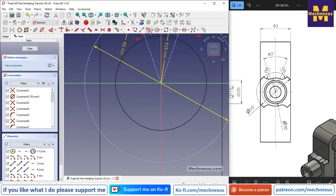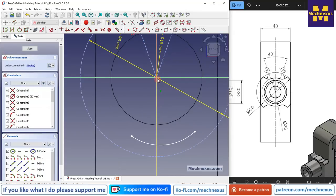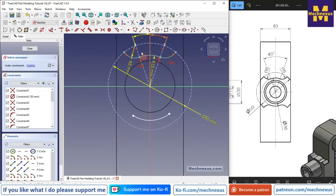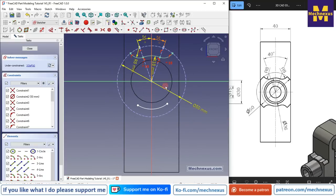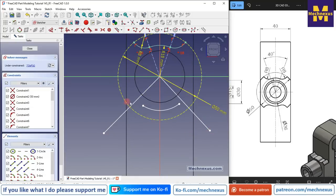So let's select a 3-point arc and we will create an arc, and here I will make it coincident, and now we will move it, and we will similarly create 2 lines of 20 degree on the bottom side. So select a line tool and create a line, and now select both and make it a construction, and here we will use the trim tool.